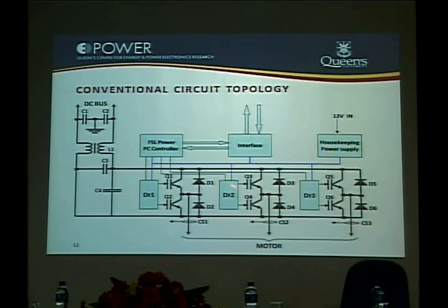These are the typical IGBT-based three-phase inverters, which produce the AC voltage and go directly to an electric machine, which is typically a permanent magnet machine in the electric car. And as we see in this one, we have some EMI capacitor, and then we have this bus capacitor here.